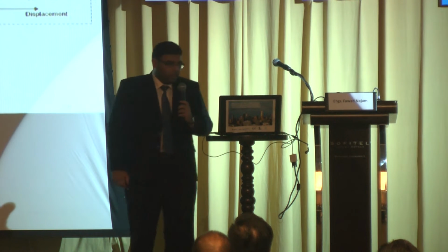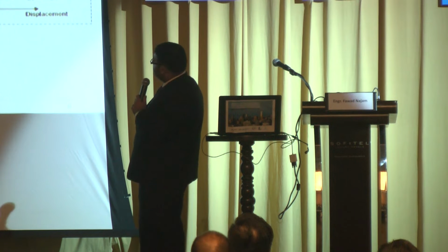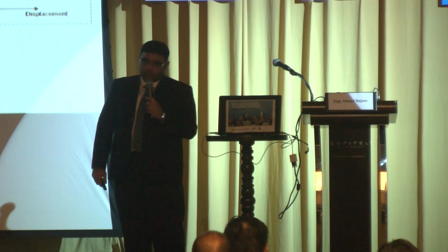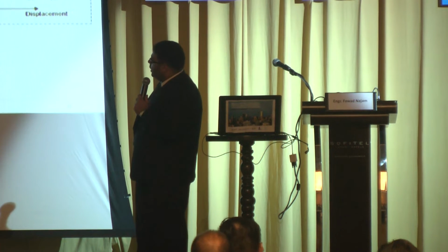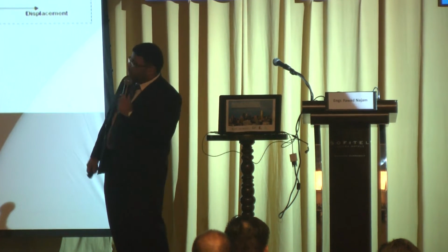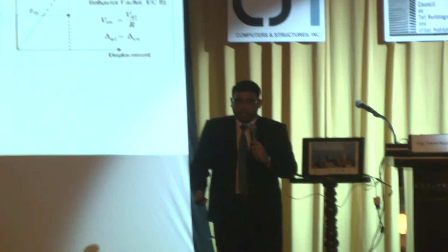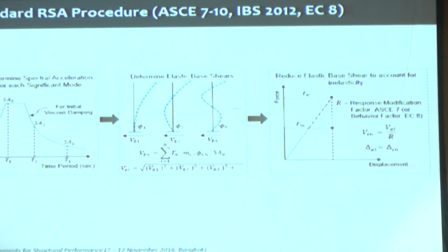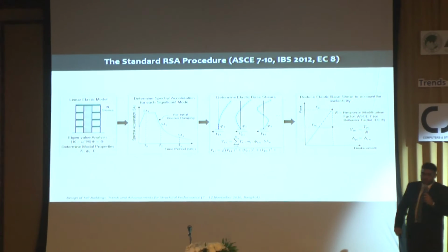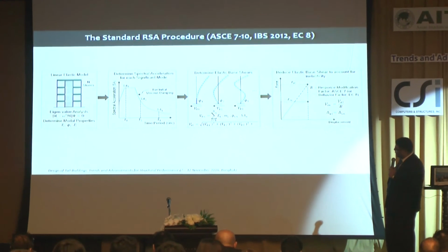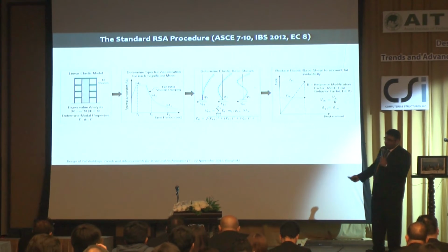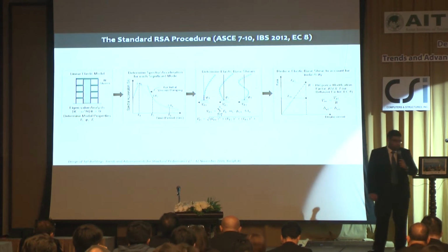Having said that, let me quickly review the standard response spectrum analysis procedure, which is the most prevailing design analysis procedure for buildings. In its current form it is available in ASCE 7, IBC, and Eurocode as well. It starts with eigenvalue analysis, modal analysis, and then you pick the spectral accelerations from a demand spectrum corresponding to each mode, convert those accelerations into forces, and combine those forces using some suitable modal combination rule.